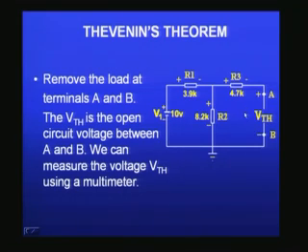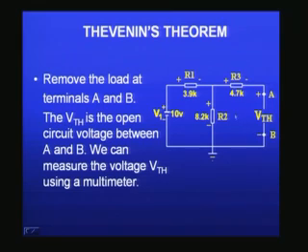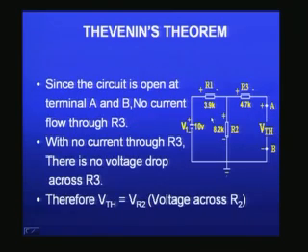If we want to calculate the V Thevenin at the output, you know R3 will not contribute anything, because this is in series with the infinite resistance here, because you are now open circuited, the RL is not there, and therefore, the voltage across R2 is the Thevenin's voltage with V1 connected to R1 and R2 in series, and therefore, all that you have to do is calculate what is the V Thevenin, which is equivalent to what is the voltage across R2.